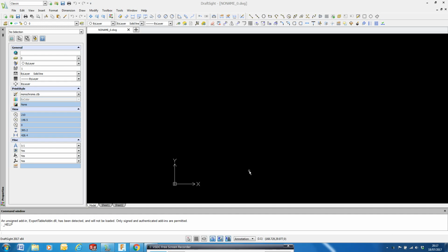So that was coordinate x comma y, typing into the command window, and the moderately useful tool was relative coordinate inputs, at comma x comma y. Pretty useful, the relative coordinates. I find it useful anyway.